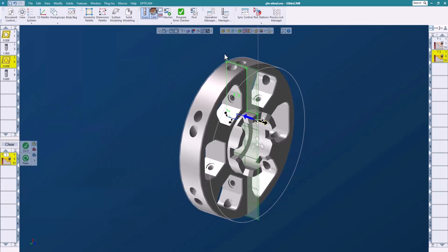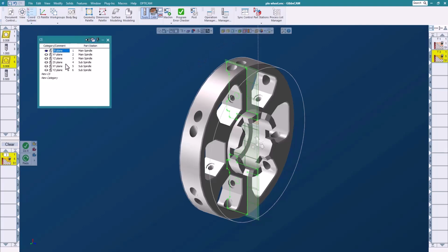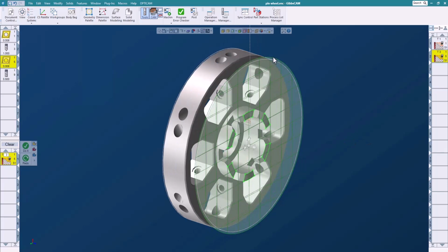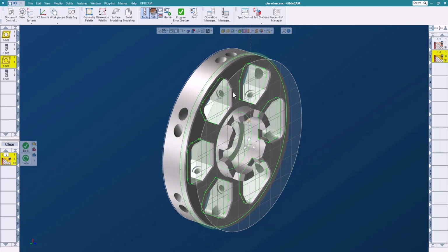All right, so what I want to do now is talk about the slice plane, because what I want to do is cut these pockets. So I switch to the slice plane, and I'm going to change the coordinate system to the XY. Now with some of the profiles, you can actually drag them around. Some are locked in the center, some are not. This one here I can drag around until I get the profile that I want. And this is what I want to cut right there.